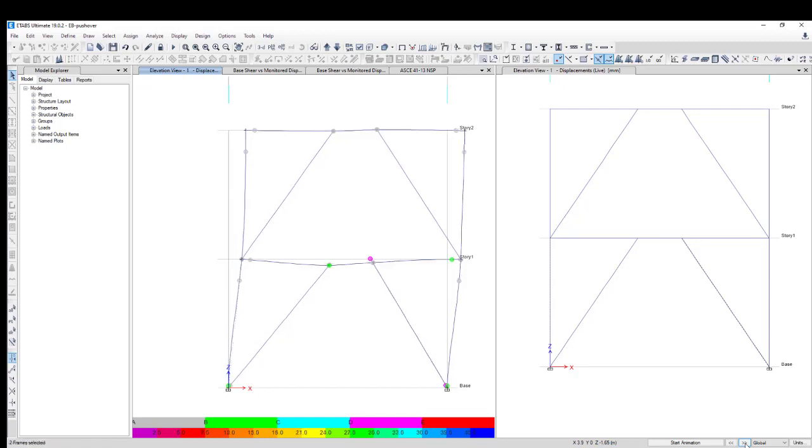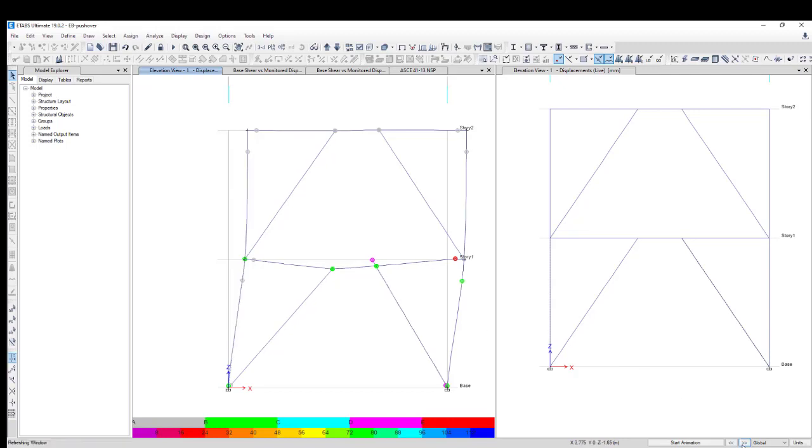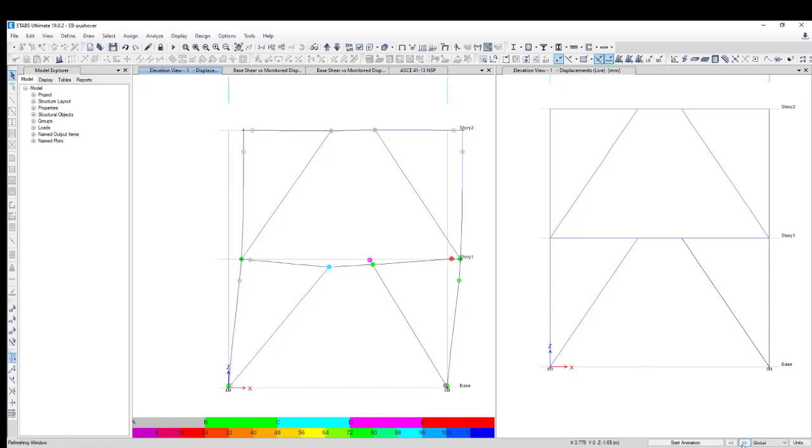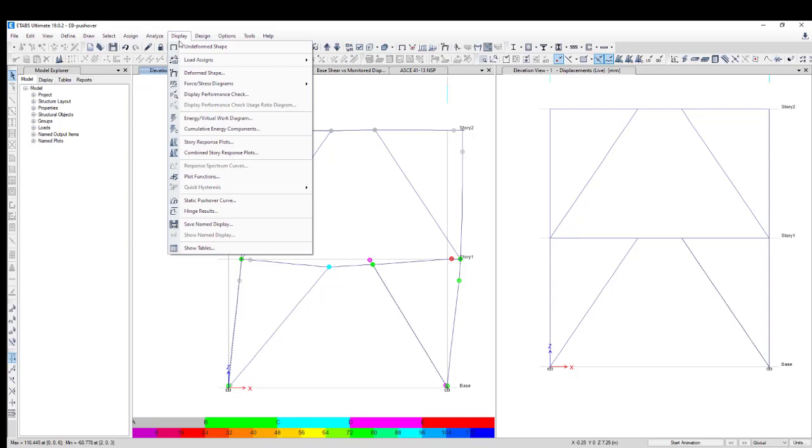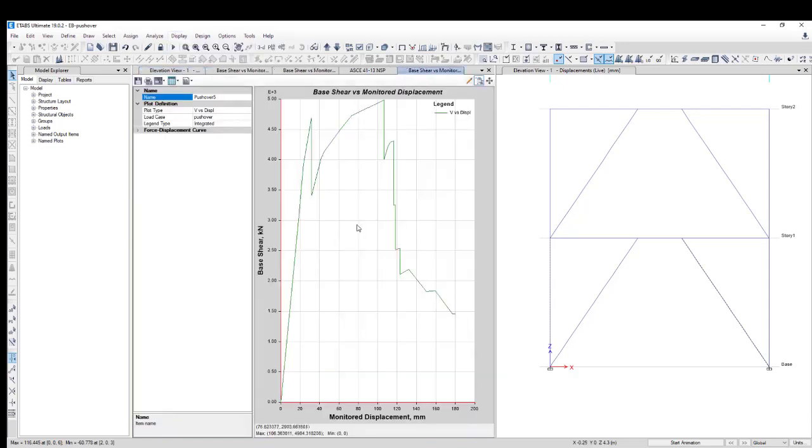and it finally changes to the first floor and this beam. So finally, in the first floor we will go to the collapse, and we can display the static pushover curves. So this is the static pushover curve. Until 180 millimeters displacement, the structure will go to collapse.